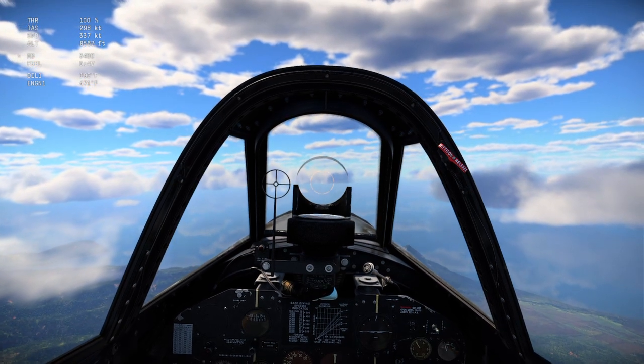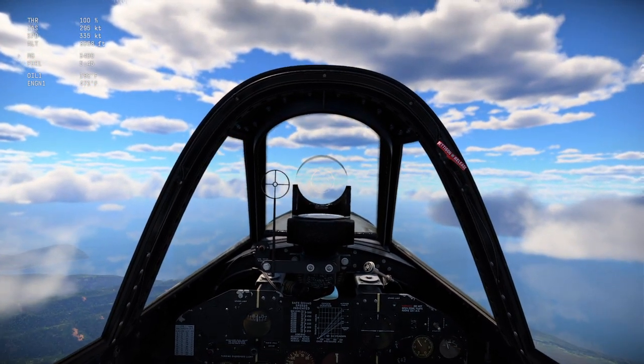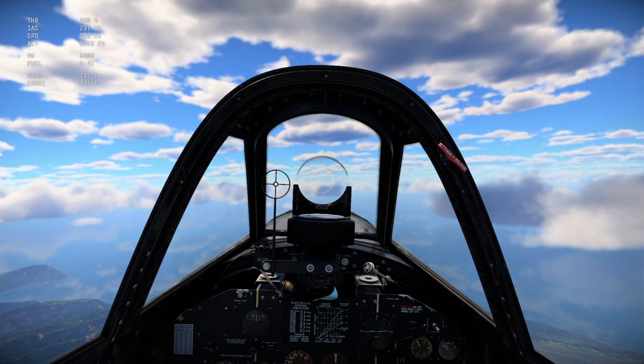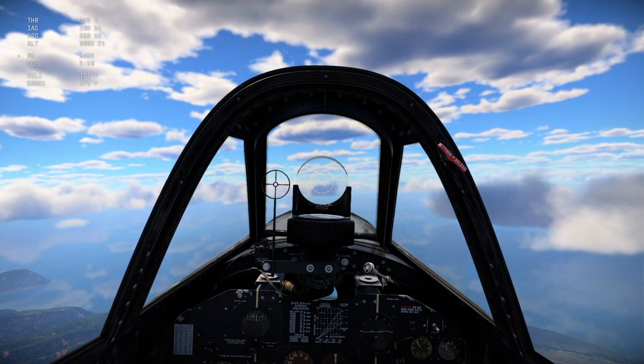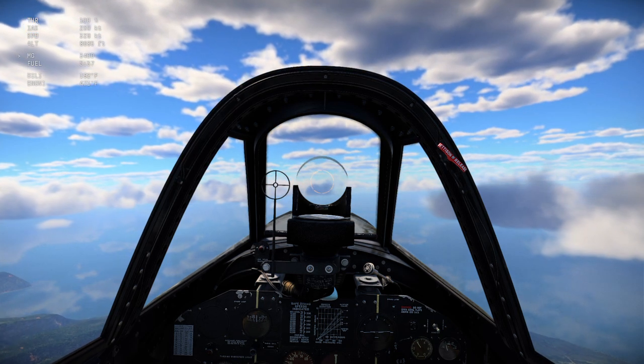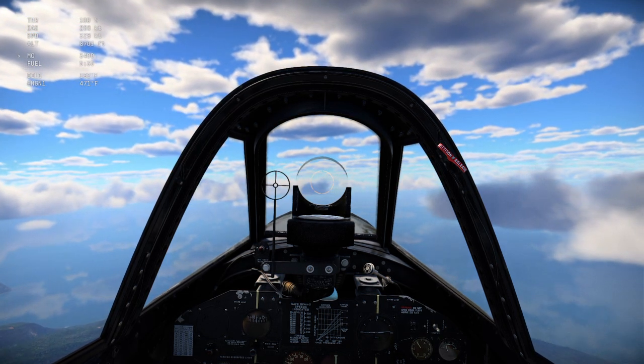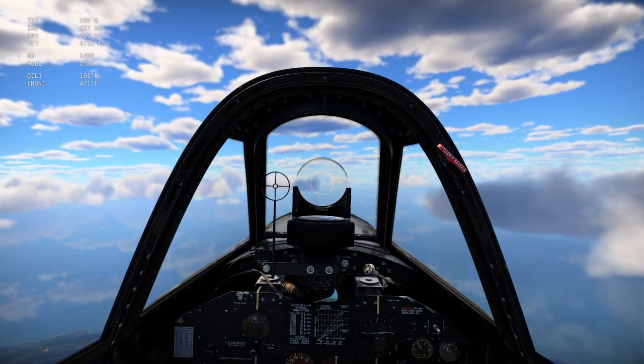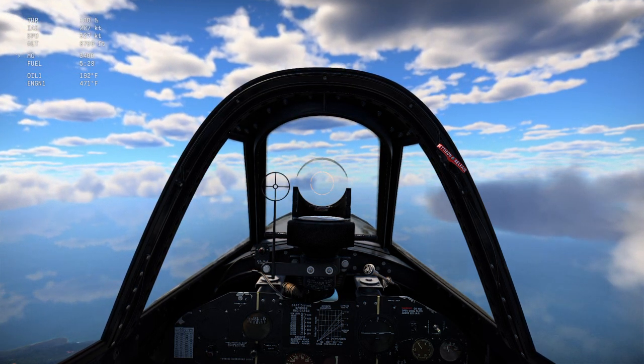So yeah, just pay attention to your temperature and just gauge it from there on what you need to do. Just remember, radial engine, air-cooled engines, start at 20. Inline engine or liquid-cooled engine, start at 40. Unless you're in a P-51, go 70. Yaks go about 60.